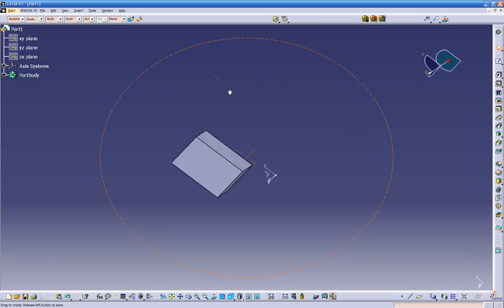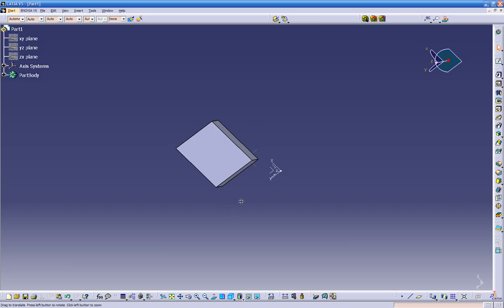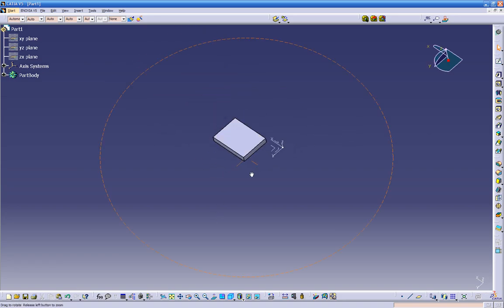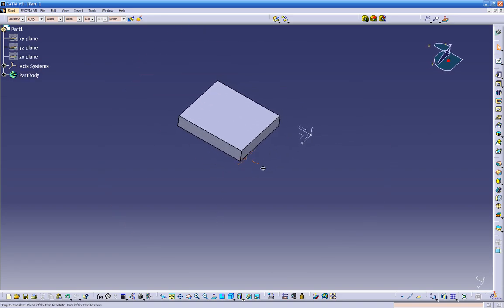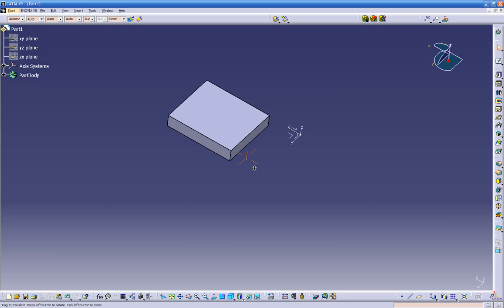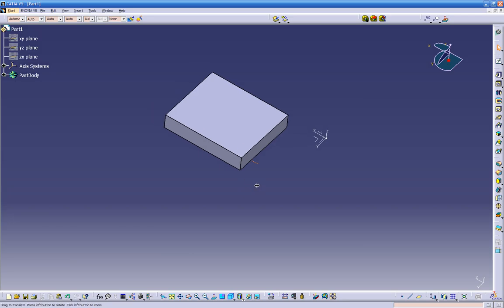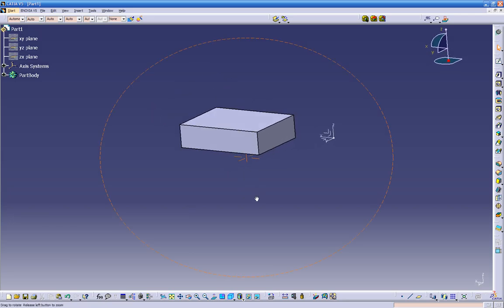Now we let go with the right click. So right now I have only middle and I have zoom. If you want to jump to zoom right away, we do middle click and tap once the right click, then we have zoom right away. It's a little bit tricky at first, but you'll get used to it.